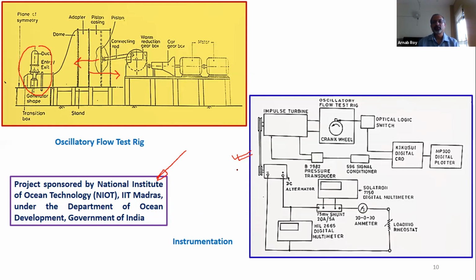So for the input power, you have to measure the pressure drop, you have to measure the flow rates, and then on the output power side, you have to extract the information about the torque generation, the angular velocity at which the turbine is rotating, so that you can quantify the performance of the turbine. And you also have to assess the losses.